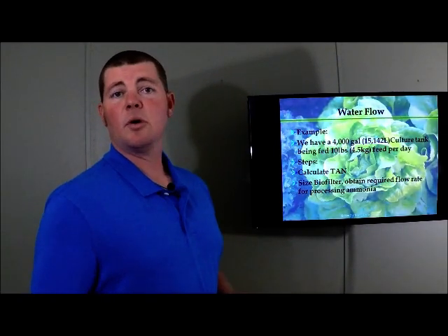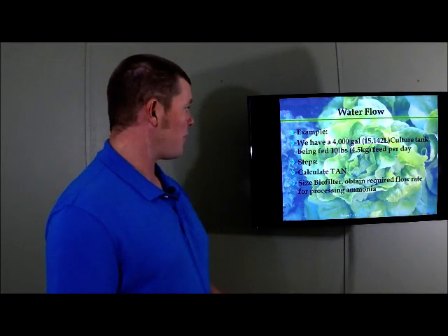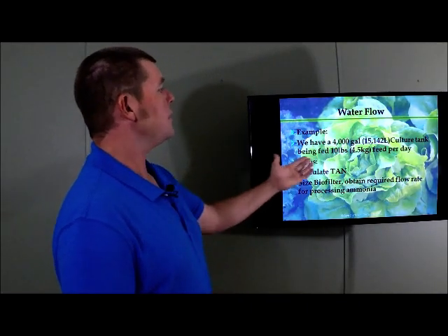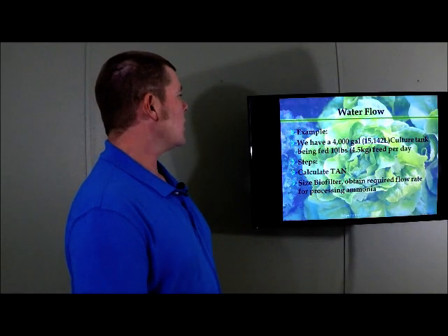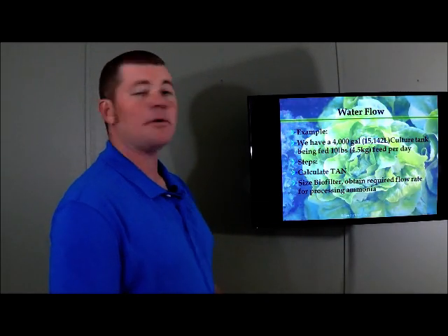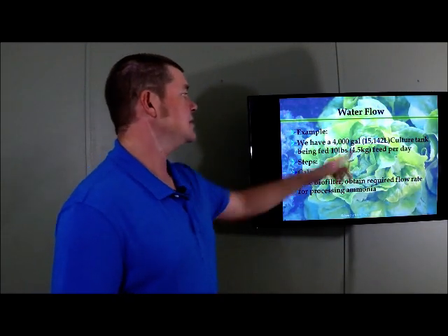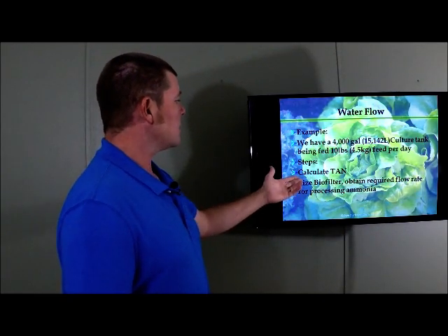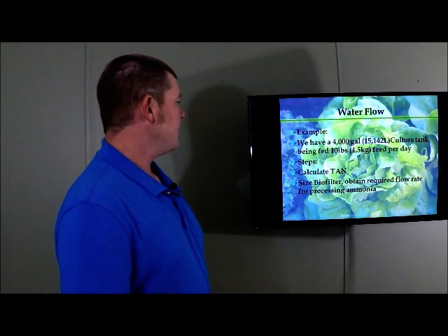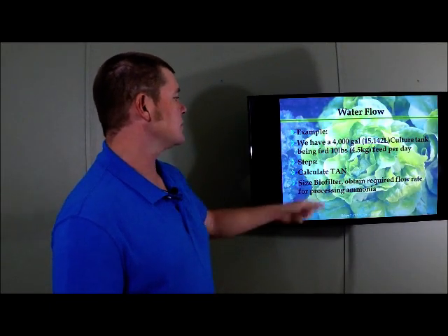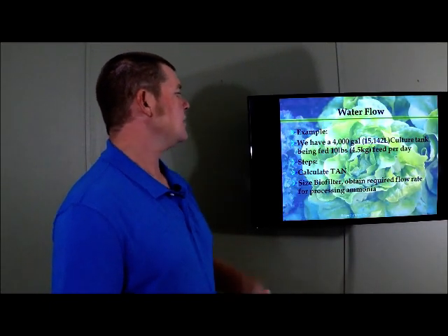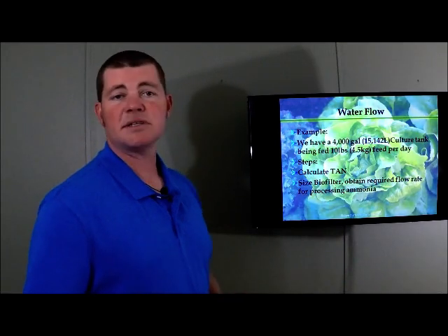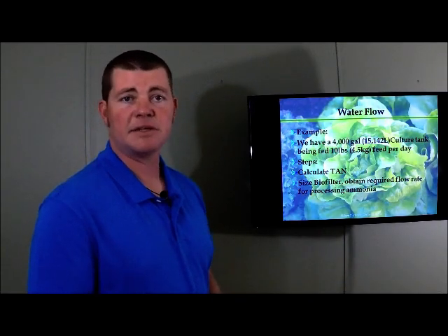So we're going to do a quick sample question or problem here. We have 4,000 gallons in a culture tank being fed 10 pounds of food per day. And again, you see the metrics here if you want to do metrics. The steps are calculate the TAN, and then size the biofilter, then obtain the required flow rate for processing ammonia. So that's part of sizing the biofilter.